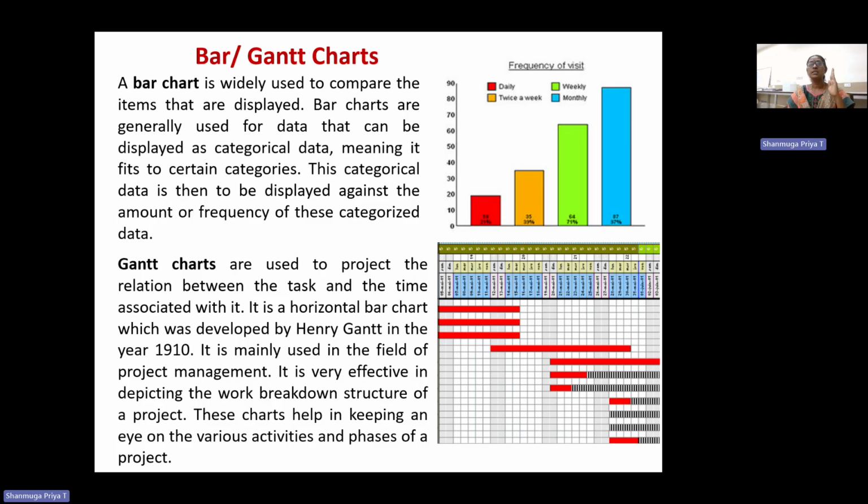For example, for an activity where 100 cubic meters of plastering work or concreting work need to be done, how many resources are required: how much cement, sand, aggregates, etc., and the number of laborers. We make these as a bar chart with reference to our construction area.